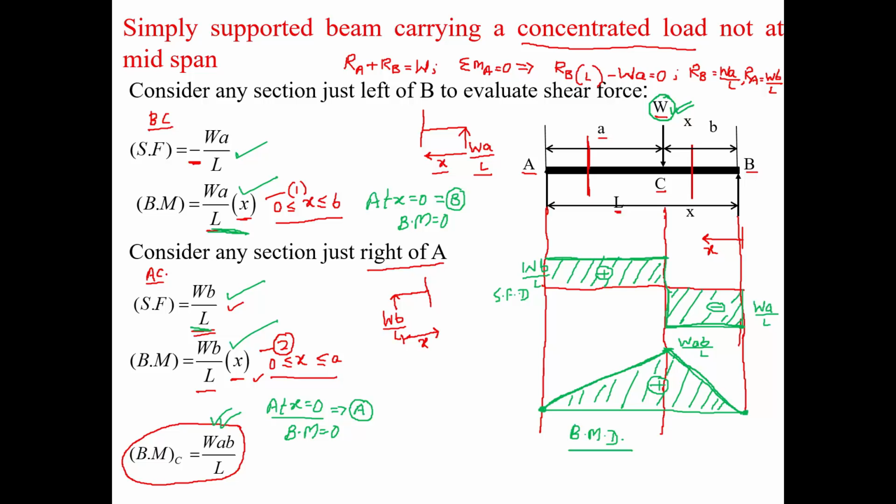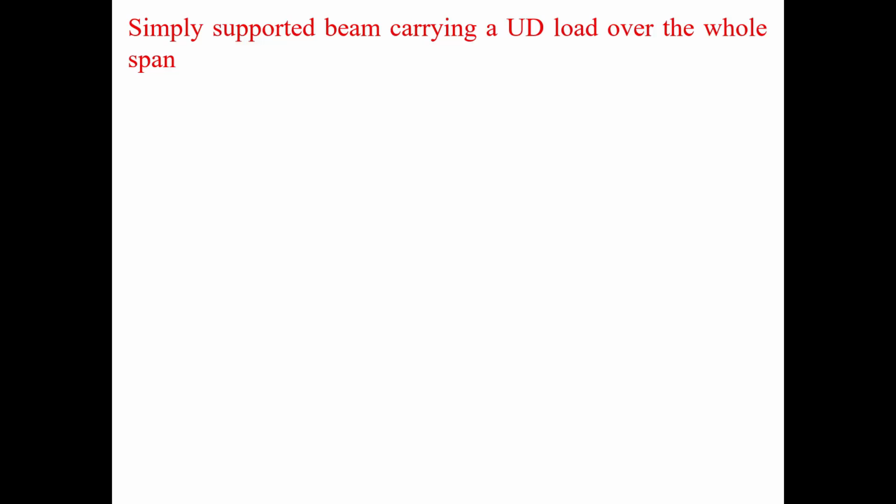So the bending moment is always one degree higher than the shear force curve. Another thing you can note is that the maximum value of bending moment arises only when the shear force vanishes. So maximum bending moment corresponds to zero shear force. These are a few observations which you can note down for your further reference. If this is clear, we can move to our next example, wherein we look at a uniformly distributed load applied on a simply supported beam, right?